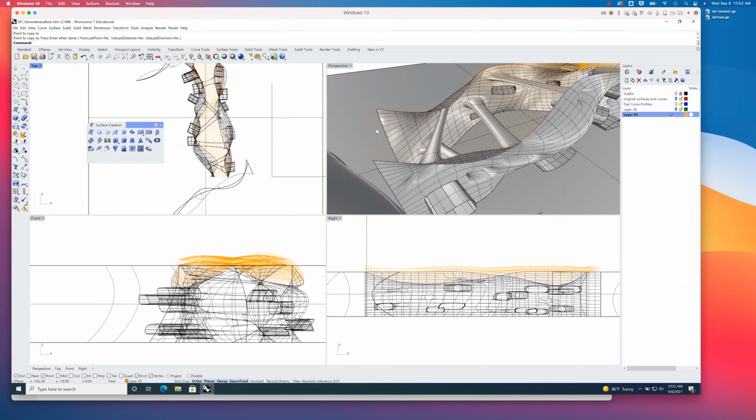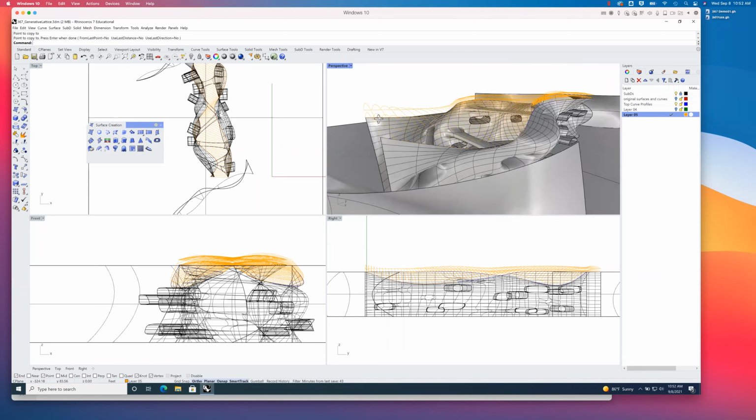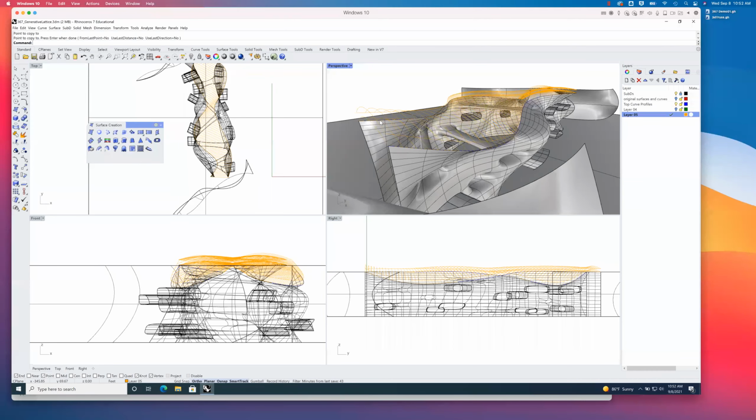All right. Now I just made a new set. The old set were selected. I'm just going to say SEL, last. That's short for select last. That'll select all of the last objects from the things that were created from the last command. So now I get those new ones.